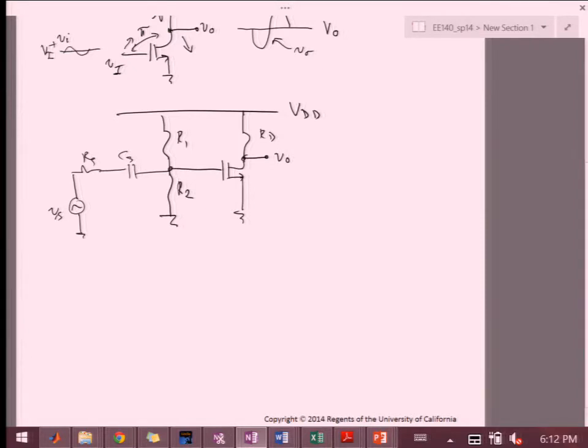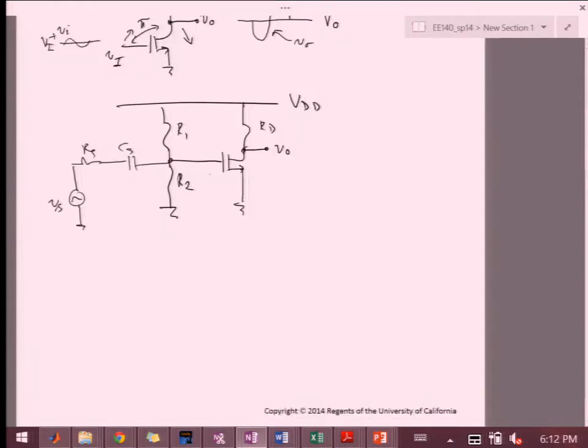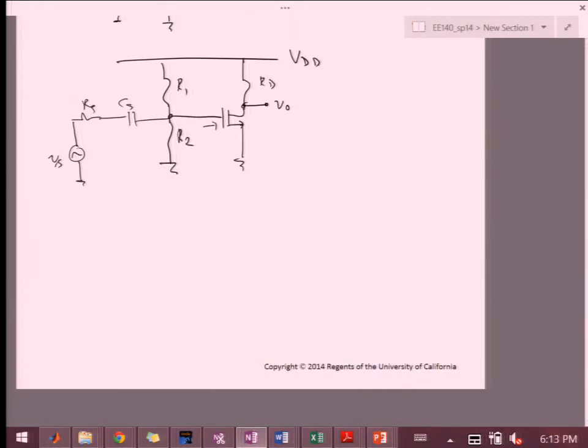Well, now we don't have that anymore. There is no current flowing here in terms of the biasing. So IG equals 0. Notice that this is capital, so in terms of DC there's no current. Of course, there is AC current, meaning a small signal variation current, but in the models that we had, because we don't have the RG, that one is also going to be 0.